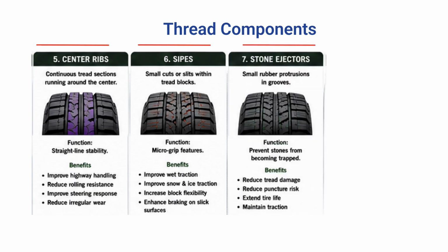Third are the stone ejectors. These are small rubber protrusions positioned inside the grooves. Their role is to prevent stones from remaining trapped in the tread. This reduces puncture risk, limits groove damage, and helps maintain traction on rocky terrain.